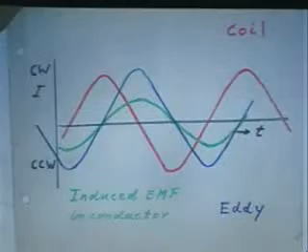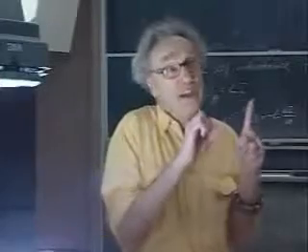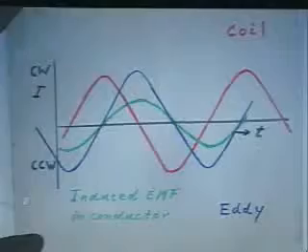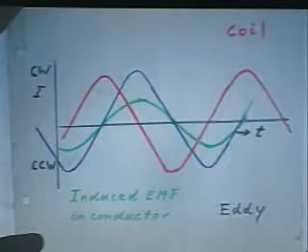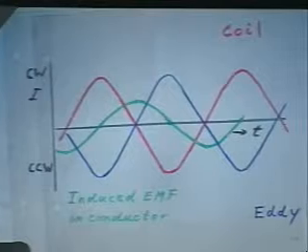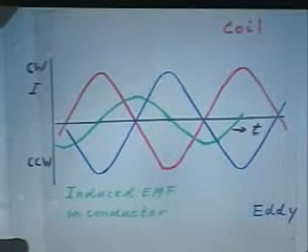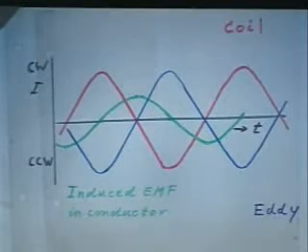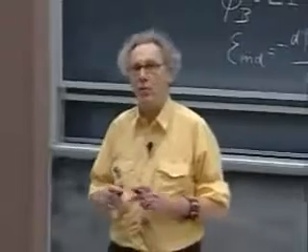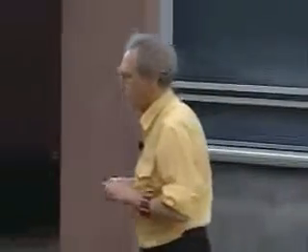But now, if I have a phase delay so that the induced current comes later than the EMF, and I'm going to do something dramatic, I'm going to shift it by 90 degrees. So the current is now 90 degrees delayed relative to the induced EMF. Look now that the red curve and the blue curve are always in opposite direction. And so now there's 100% of the time a repelling force. The coil repels the conductor, and the conductor repels the coil.